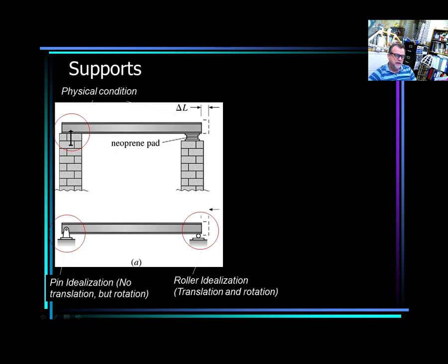Now this one here, if I get this part, I can lift it, and this is going to have a rotation. And one of the things that you have to start getting around is that when I say rotation, it doesn't mean that it's going to be rotating freely around the circle. No, it should be like that. But if you have a little rotation, that means that the moment is not restrained over there, and it's free to rotate. That means there's no moment reaction. However, I cannot push it because this bolt is preventing that sliding, and at the same time, if I get this, I cannot lift it because the pin is preventing it also with the nuts and the washer, meaning this is a pin for practical purposes.